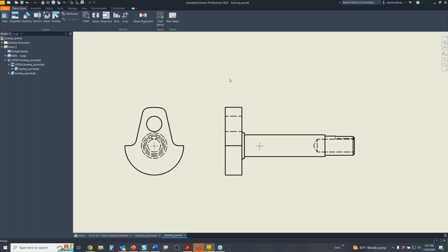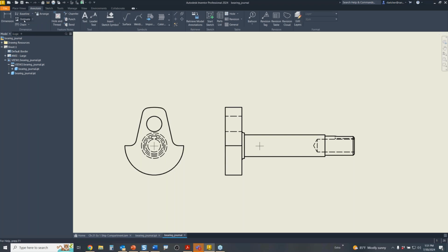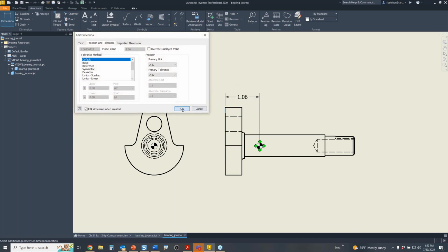And then immediately someone in the class asks, well, how do I get the center of gravity symbol? Now, I made this one up on the fly, but it works really well. Use the ordinate dimension. Grab the ordinate dimension, select the view, and you can drop in the origin marker and just right click, continue, hit enter. And there you go. If I do it again on this one, just select the view, drop off the marker, right click, continue, and there you go. So now you've got your center of gravity, and you can dimension to these things. Make it very easy for yourself.